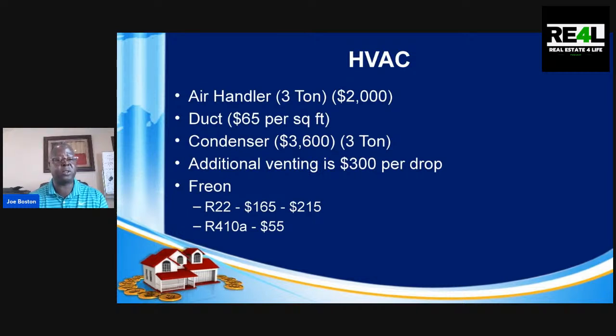And then Freon. The older systems use what's called R22. This is the coolant. But now the systems that are more efficient use R410A. And the R22, because it is not as efficient and it's pretty much been removed mostly from the market, is higher in price because the availability is not there. But a lot of the older houses will have R22, and more than likely your HVAC rep or company is going to recommend that you replace it. So don't be alarmed if they do, if it starts to run rough.